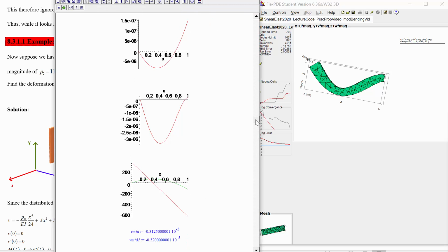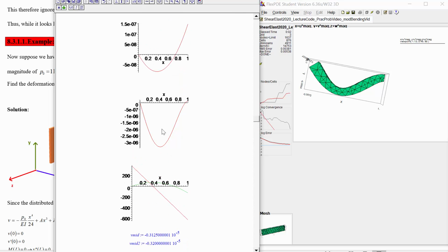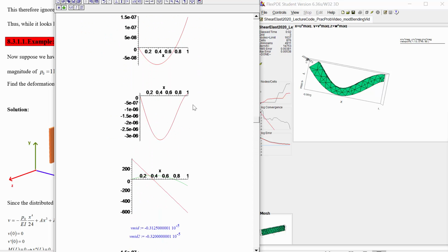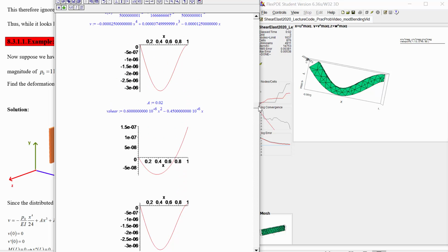Now, if you look closely, you can see the limits of this analytical approach in Maple by noticing that the shear is predicting that we don't actually go back to a 0 displacement at the other end from shear alone, but it definitely should be doing that from the shear alone displacement. And if you're going to sum these in superposition, we should be ending up at the same spot as before. But we don't. So this is a bit of an error in this current approach.